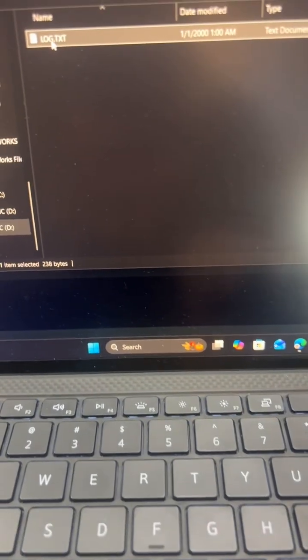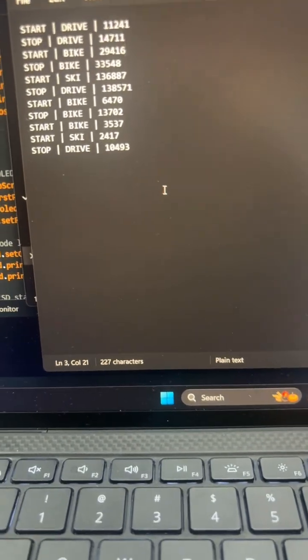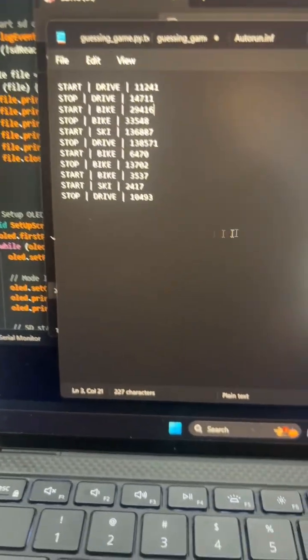It'll open this log text, and this just shows the data it just recorded and how we cycled through each mode. From here, we just need to get our IMU working and use our Nano to build off of our basic functionality more. Our main struggles so far have been the faulty GPS and the Uno R3 not having enough memory to demonstrate everything we're trying to do.